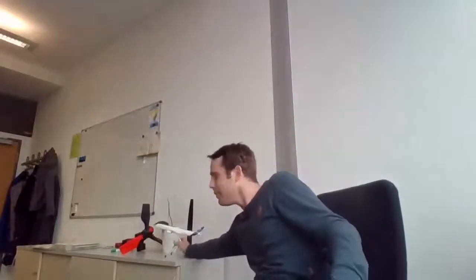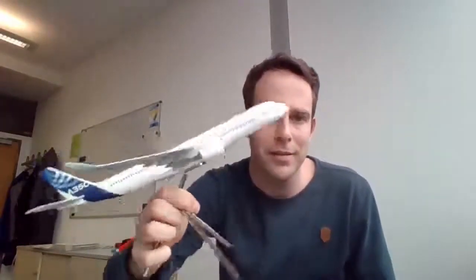Your aircraft, your autopilot for holding the altitude, right? If you have a control system which only can do this, this, and this, it's probably not going to work. You really need a smooth behavior of your aircraft. This is where linear controllers come into play. If you want to build a cheap oven, a cheap espresso machine to hold the temperature, a bang-bang controller can do it. So this is really a design decision.